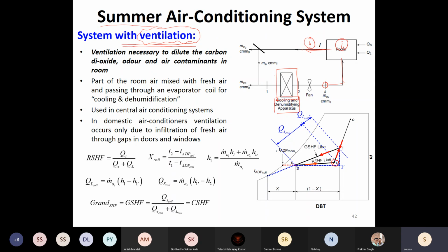So this is your return air, or sometimes also called exhaust air. Okay, and this is your supply. So in your classrooms also, when you visit next time your Nalanda classroom, you can see that there are two ductings provided. One actually brings in cold and dehumidified air, and the other ducting is for the return line. Same if you visit any mall, any commercial space, you can check that there are two sets of ducting always provided.